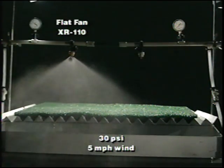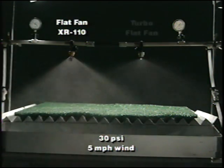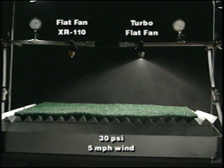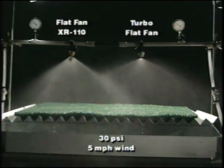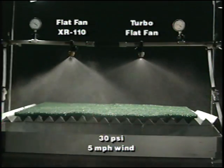Here's a flat fan extended range 110 nozzle, demonstrated at 30 psi with a 5-mile-per-hour wind. Compare this nozzle with another new design, the turbo flat fan, under identical conditions. And now, side by side. As you can see, the turbo nozzle design is obviously a better drift performer, especially under windier conditions.